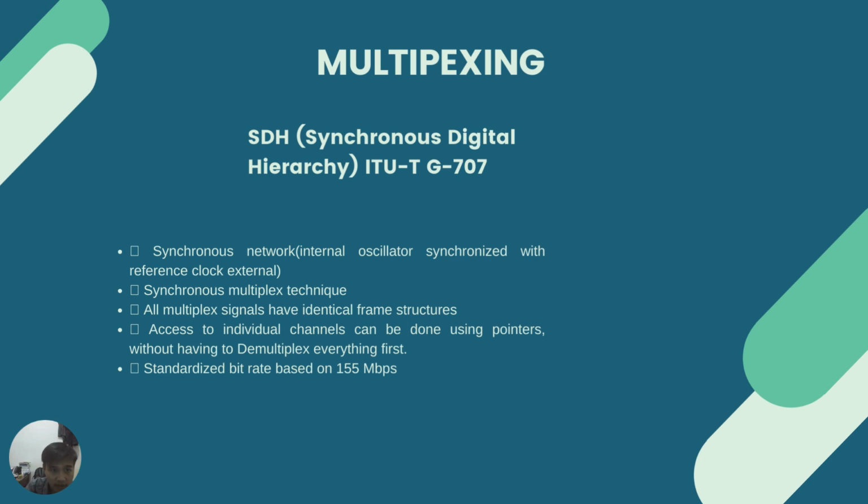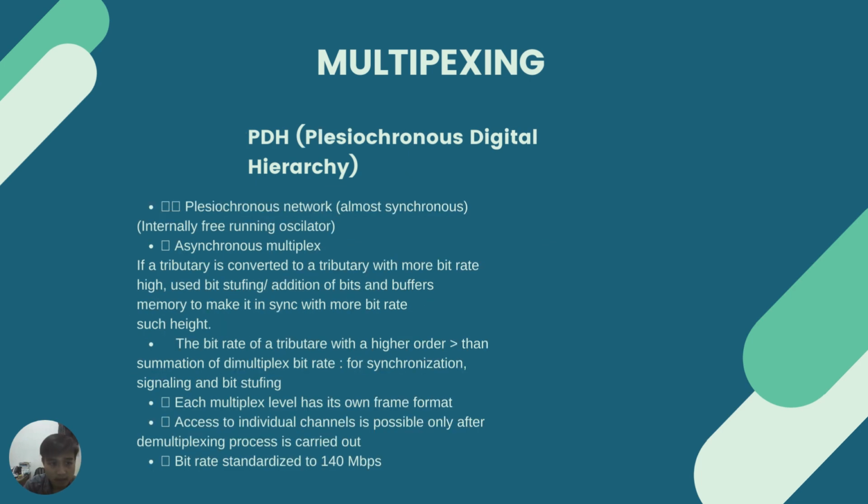And then this one is SDH, I mean synchronous digital hierarchy, and the synchronous network has an internal oscillator synchronized with a reference clock, an external one. So with the synchronous multiplexer technique, all of the multiplexed signals have identical frame structures, and access to individual channels can be done using pointers without having to demultiplex everything first, and the standardized bit rate is based on 155 Mbps. So this is more than PDH, I think.